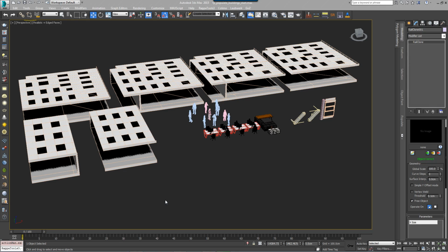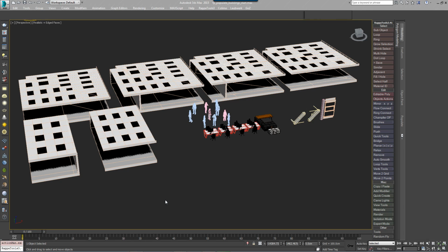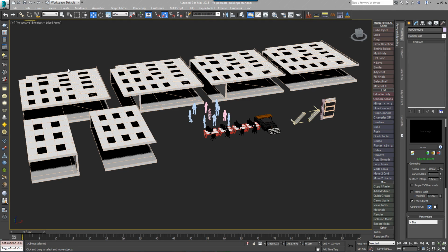Instead of creating a stack of surfaces, we can use it to add a two-dimensional array of rooms around the perimeter of the building. This style uses 2 room segments, one with and one without a wall, and 4 corner segments with some different internal wall configurations. The more of these you add, the greater variation you can achieve inside the building. These rooms have already been mapped so that the perimeter UVWs are moved to the black area of the existing distribution map using the technique we've just discussed.